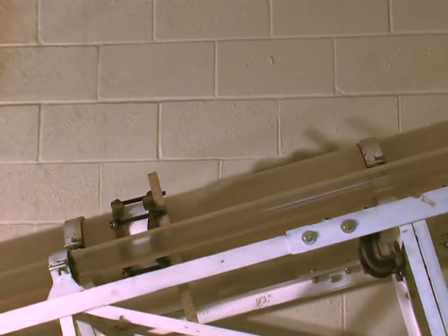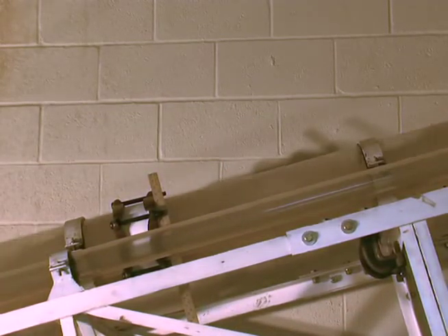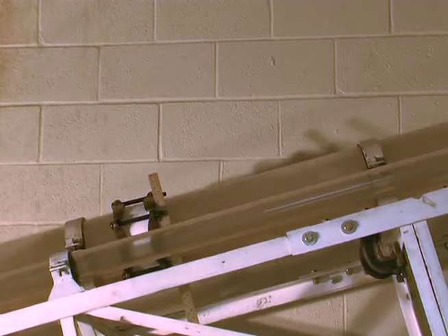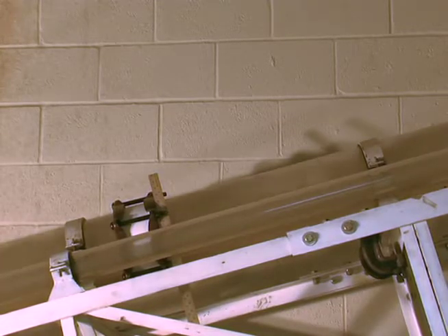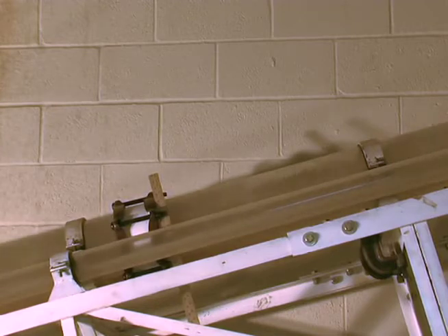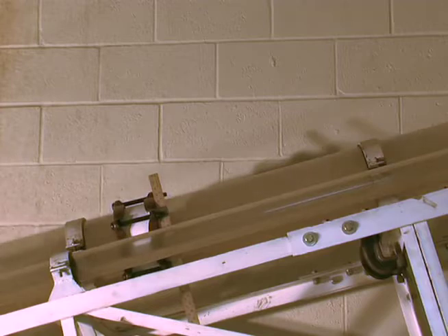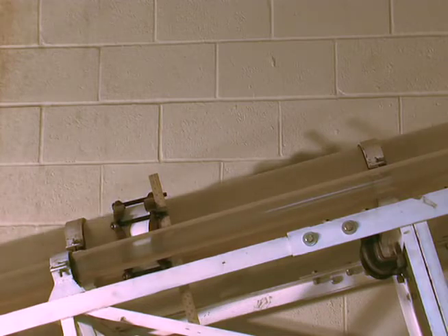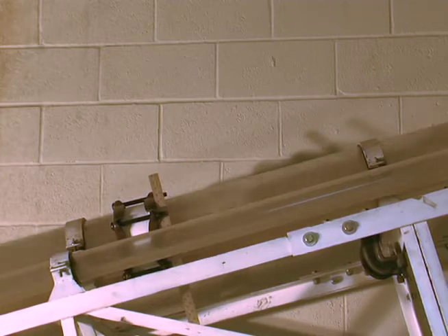The flow tube angle has now been increased to 14 degrees. The water rate remains 628 barrels per day, but the gas rate has been reduced to 70 MCF per day. What you see in the large tube is intermittent plug flow, where bubbles of gas are moving along the top of the tube. And in the small tube, you see a stratified wavy flow where the waves are made up of long sections of foam.